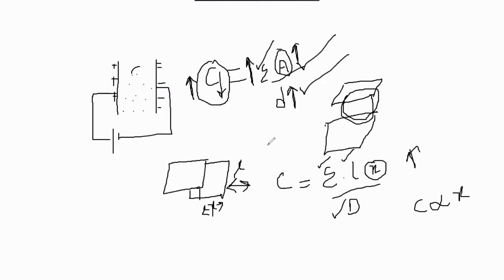Circuits. So you can measure the change in capacitance from the bridge circuits, so the bridge will become unbalanced. Now we can measure the output voltages. The same principles also apply in the capacitor transducer. The same principle follows. In this case, the first condition is a changing overlapping area.